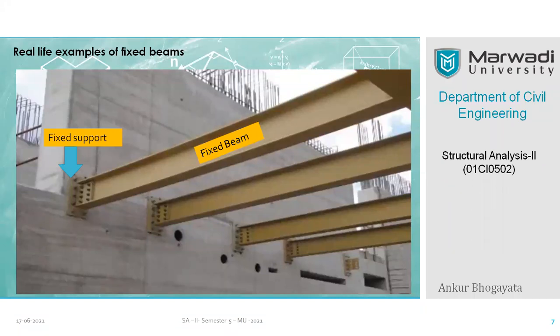I'm giving you a logic. When you load the beam, the beam has to bend. Now to bend, the beam should be continuous, right? So the moment you connect one beam with another beam with non-fixed types of joints, at that junction the transfer of moment will not be possible anymore. So we cannot classify or qualify that element or arrangement or extension as a beam itself.